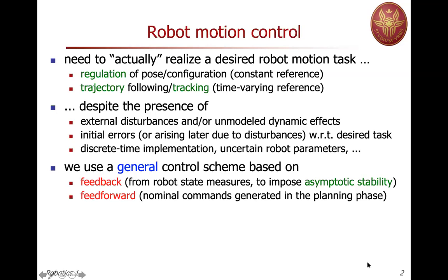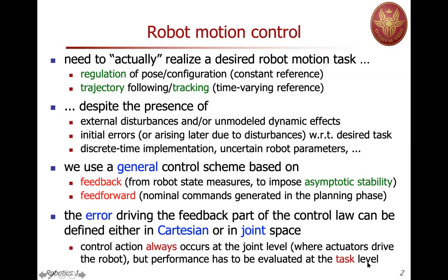It's true only for some research robots, like the KUKA lightweight robots, not for a general industrial case, where instead we have a closed architecture, and we cannot enter into the heart of the controller. We can just modify the reference in terms of kinematic terms. This may be done at the position, velocity, or acceleration level. Typically, the velocity level is the most used.